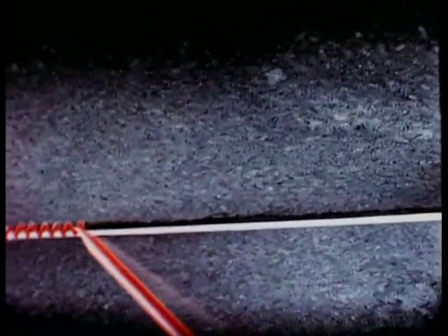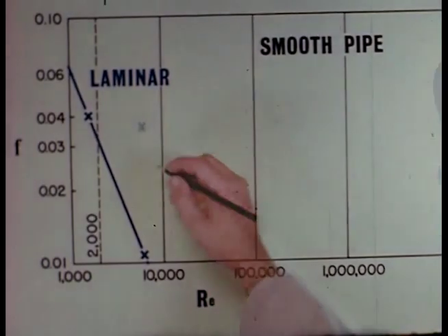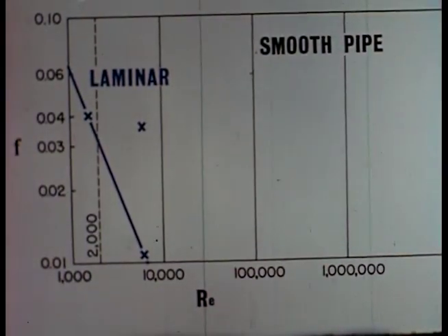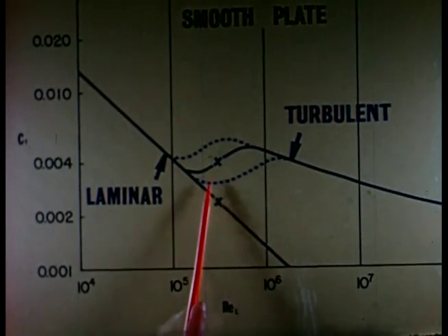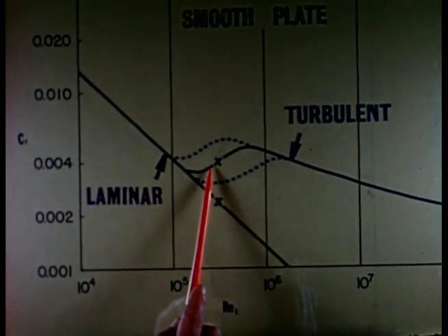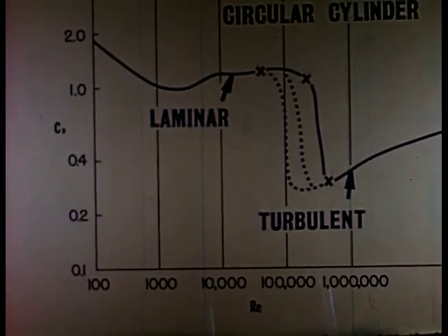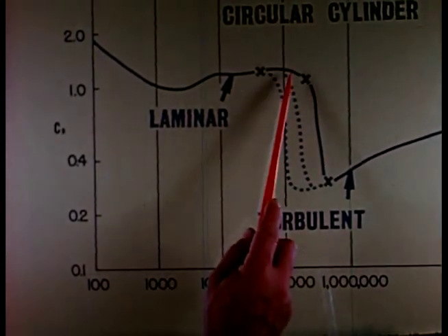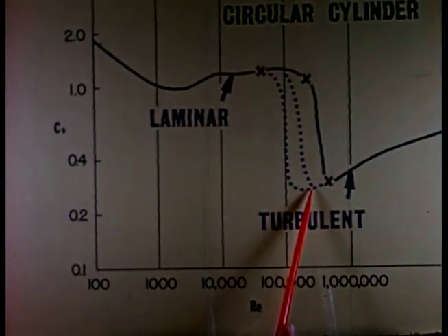Thus, in a certain range of Reynolds numbers, even a few roughness particles may serve to increase the head loss, or drag, where these are largely frictional. Or, on the other hand, may serve to decrease the drag when drag is largely due to separation.